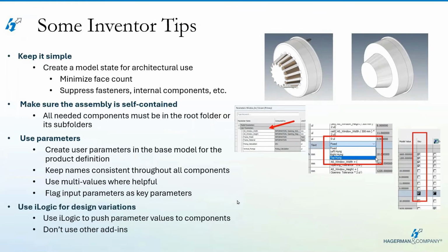And click again, please. iLogic itself is what's going to be used to push the parameter values. So if I change the size of the opening or the desired window, that's got to go down to all the framework and all that. So yes, push it down via iLogic pushing parameter values. At this point, iLogic is the sole supported add-in. I hate to call it an add-in because it's not anymore, but it's the sole supported one.